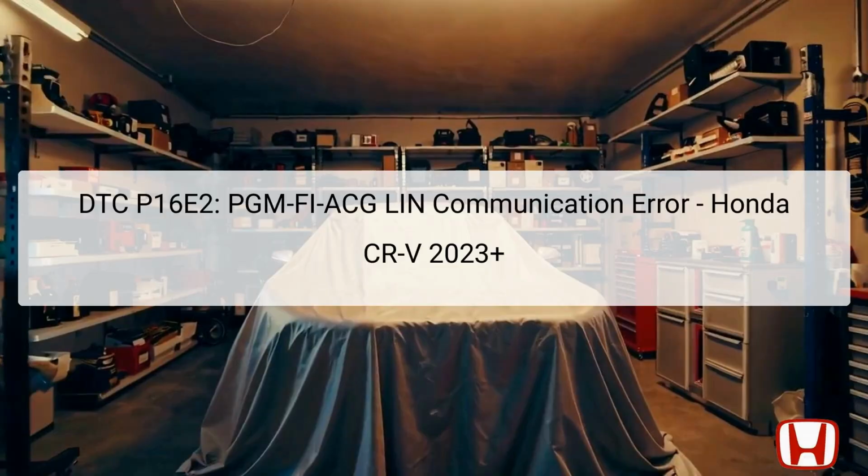DTC P16E2 indicates a PGM-FI-ACG LIN communication error, specifically related to the Honda CR-V model manufactured in 2023 and later. The acronym PGM-FI stands for Programmable Fuel Injection, while ACG refers to the alternator control generator.